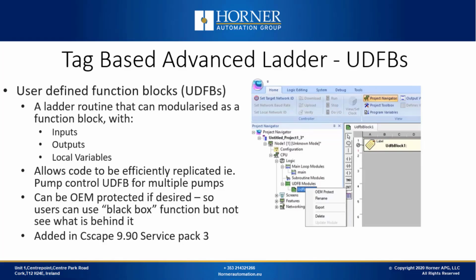User-defined function blocks, or UDFBs, are ladder routines that can be modularized as a function block, where you assign inputs to the block and outputs to the block, and local variables used within the block. UDFBs allow your code to be efficiently replicated. So for example, you could create an application for controlling a pump, and if you had multiple pumps that are controlled the same way, you could replicate your logic across all the pumps through creating a pump control UDFB.